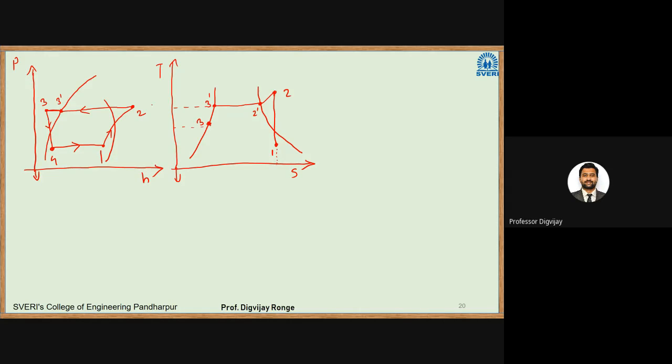So this is your T saturation, and here, as it is subcooled, the temperature is lower. From this, the isenthalpic process is shown to point 4, and 4 to 1 is evaporation. As I said, drawing the diagram is also a most important thing. Now we'll solve the problem.